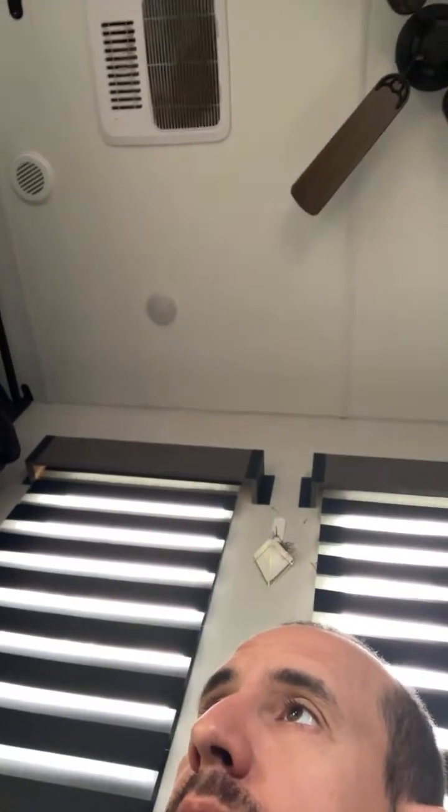So what should you do? Reduce power, reduce climb rate, enrich air fuel mixture, and open cowl flaps if equipped.